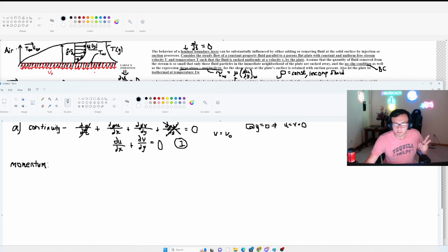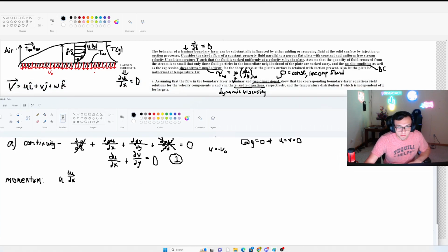It's two-dimensional, so x, y. And incompressible fluid, non-slip, uniform free stream, all those conditions, this is what it comes out to. So u, small u, this is a component of velocity, over that same thing over x. Also, it's minus. This is negative. The reason why this is negative, by the way, is that this is the rate at which it's suctioning the fluid out of the sponge, because it's coming out of the sponge. If you're putting stuff into it, injecting fluid, it'd be positive, but we're taking stuff out in this case. So this little v, which is a component of velocity, is equal to this rate, negative, because it's coming out.